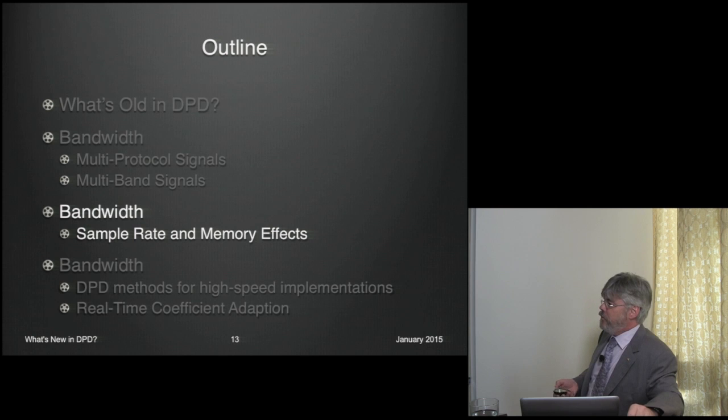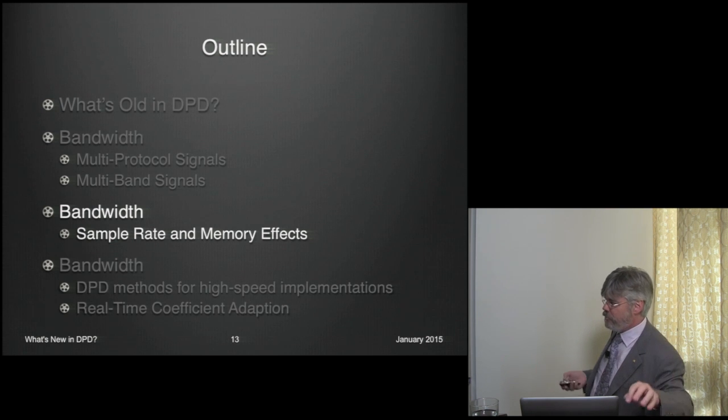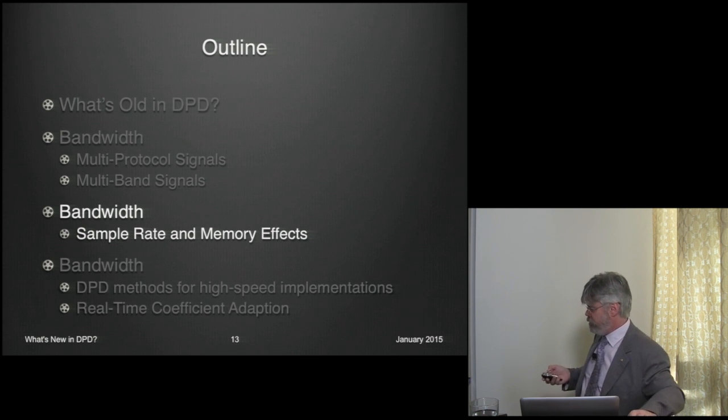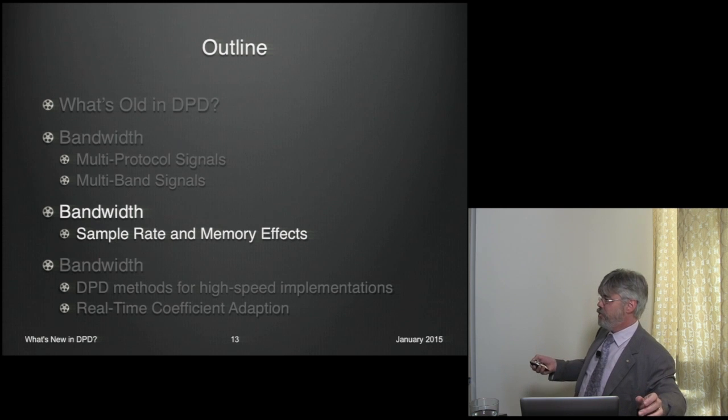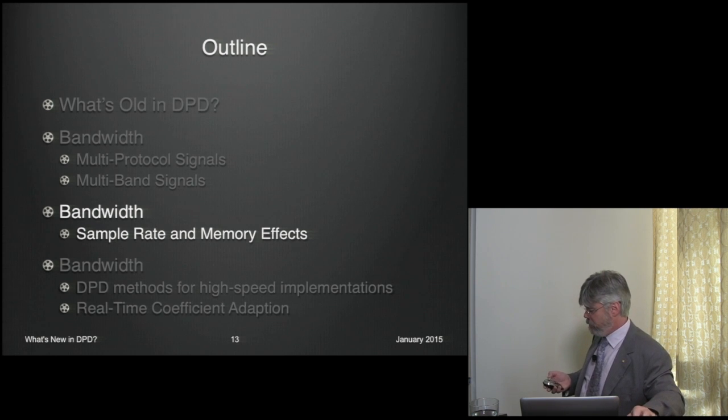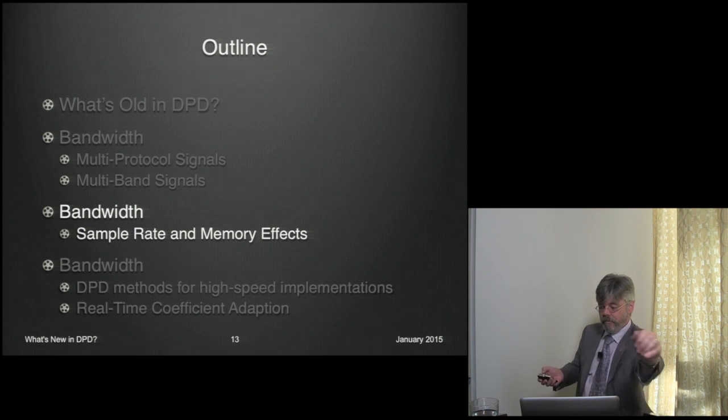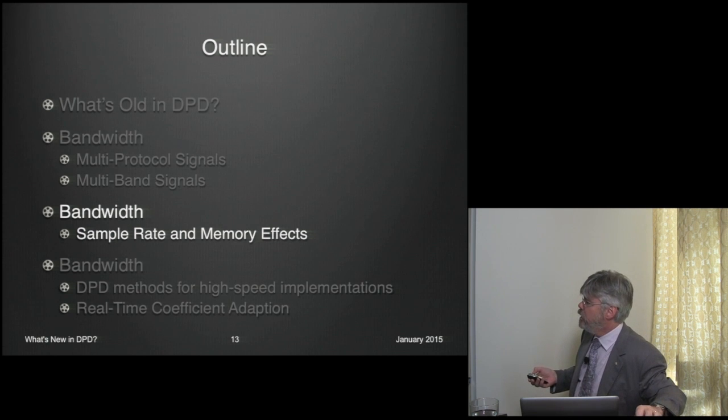If you increase the bandwidth, then to accommodate that amount of signal instantaneously, you're going to end up clocking the digital system much faster. So that's one aspect. The wide bandwidth will also give rise to some memory effects. Frequency domain, frequency response effects are one of them, and others are due to a whole range of maybe thermal effects and other charge storage effects in the system. I think we're doing okay.